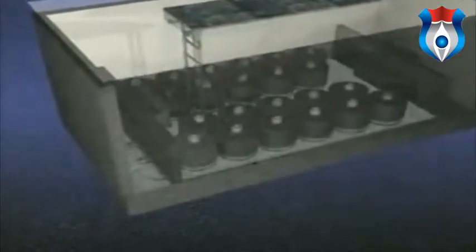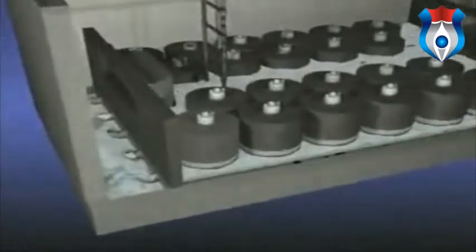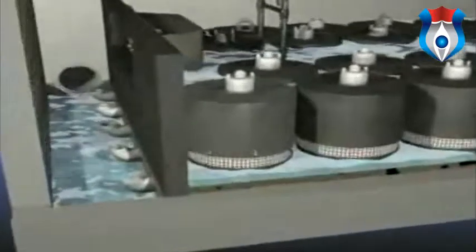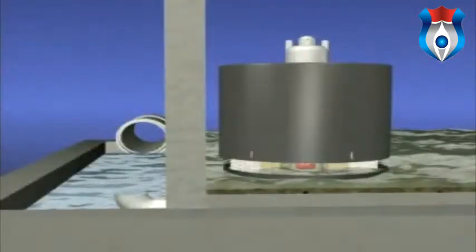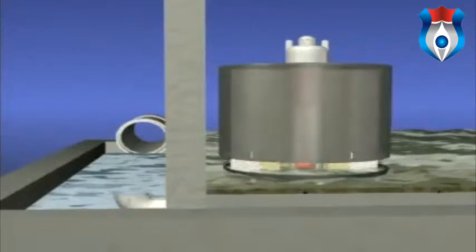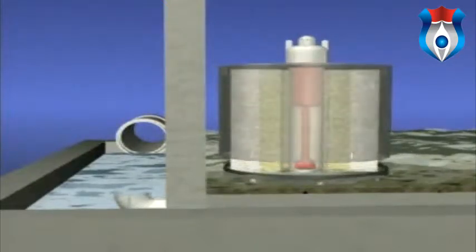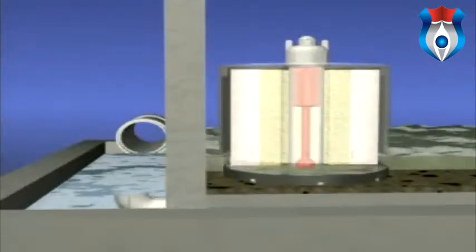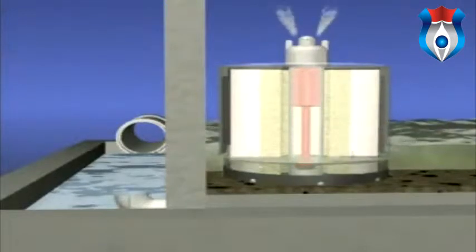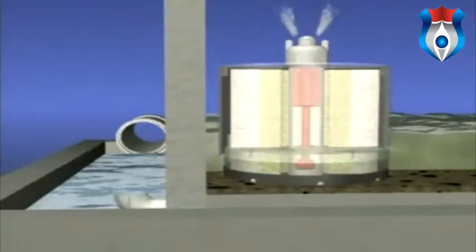The storm filter is a simple yet ingenious design that puts the forces of nature to work. A concrete vault collects the polluted water, and before it leaves, it passes through these filter cartridges. The key to the system's efficiency is in the cartridge. Inside is granulated media, natural and synthetic products that remove the pollutants. During a storm, the float system in the center of the filter cartridge helps prime a siphon that draws the polluted stormwater through the filtration media and into a center drainage tube.